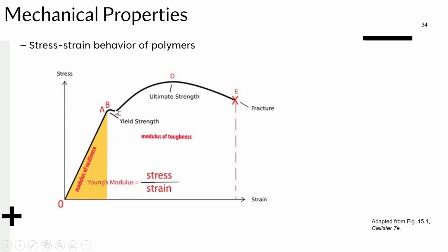You have a necking phenomenon happening, and the cross section is reduced, and then you can still continue stretching it beyond that point to high strains, and then you can observe it reaching the point of fracture beyond the ultimate strength. So you have the elongation at break here, and before it reaches that elongation, it has an ultimate strength at some point in between. This is the typical behavior of the stress strain curve of a metal.